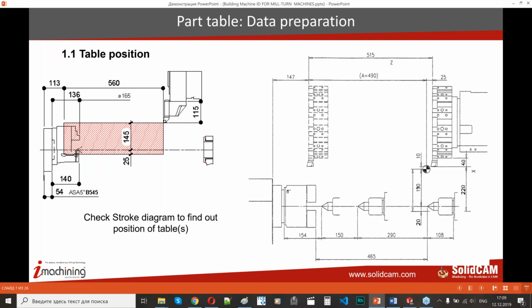That means the main spindle is the basic device to construct an axis layout. But the confusing thing is that both diagrams are showing two different positions on the spindle for the upper and for the lower dimensions chain. We can get an answer to this misfit if we look more closely at the spindle itself.